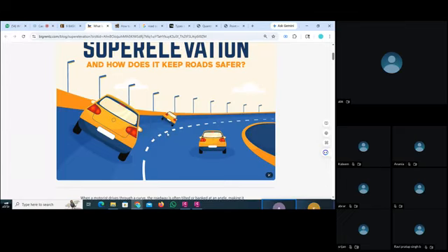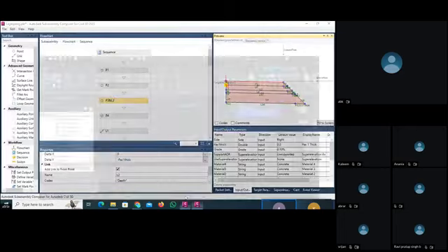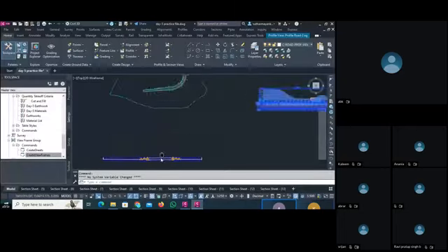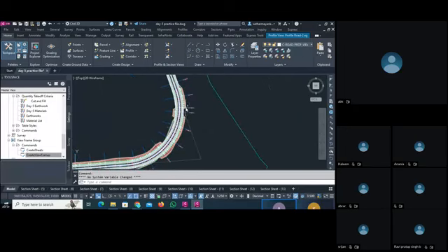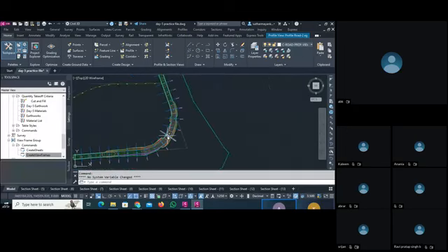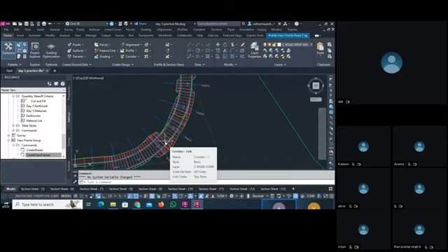So once you go through the theory, you practice this here in our Civil 3D also. You check all these things, how your curve is created. You give the label here. You check your radius. Then in AASHTO there are equations for calculating the super elevation. For that you need the f value, the length, the slope value, and the design speed. With the help of these four things, you can calculate your super elevation manually too.